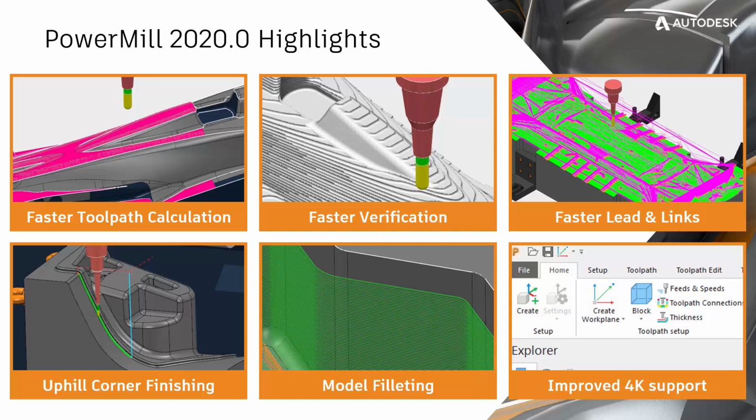It offers major benefits, and as I mentioned before, it basically applies fillets to the internal corners of 3D CAD models during that toolpath calculation, and it helps minimize the likelihood of tools engaging into heavy stock. And those 3D models are cached with the toolpath, so they aren't recalculated unless absolutely necessary.